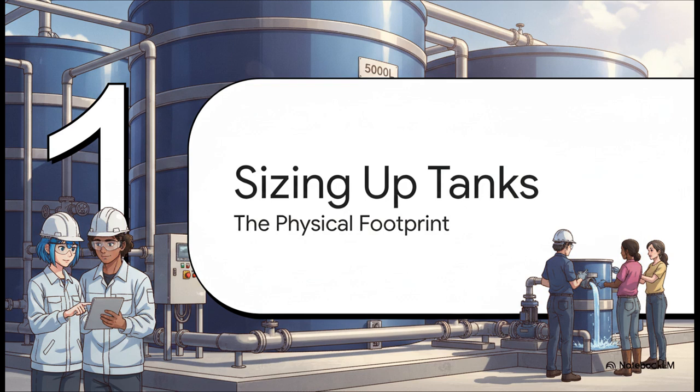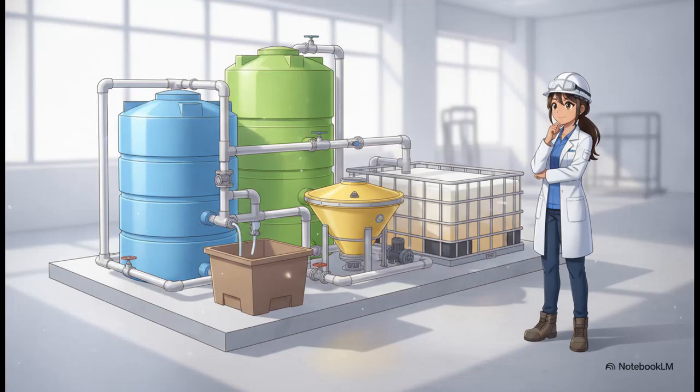All right, Section 1. Let's size up these tanks and look at the actual physical footprint we're dealing with. What's really interesting here is just how compact these tanks actually are. You start with a screen and equalization tank at around 3,000 to 5,000 liters, just to catch the incoming debris. Then the water spends hours in the aeration tank, which needs to be your biggest one, at 5,000 to 7,000 liters. After that, it moves over to a settling tank of roughly 2,000 to 3,000 liters, and then finally into a 3,000-liter treated water tank. Whatever gets separated out goes into a small 1,000-liter sludge holding tank.